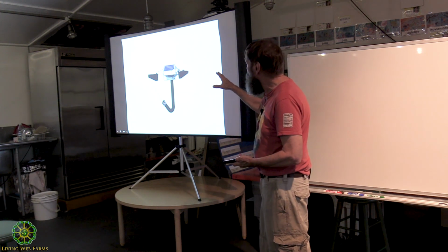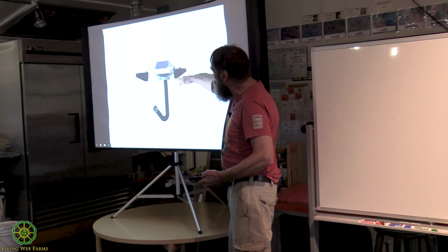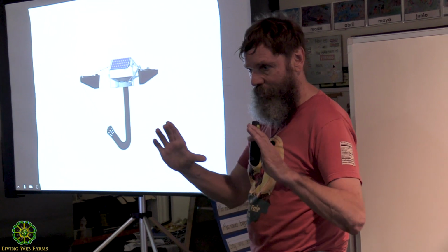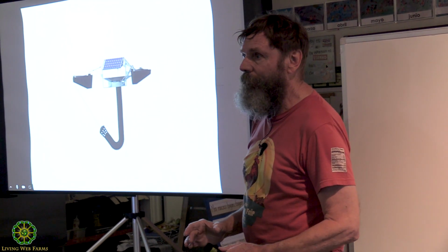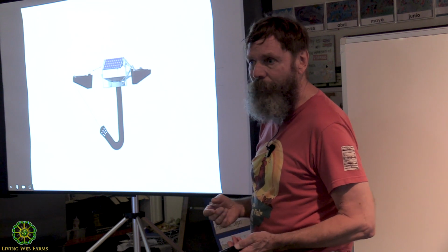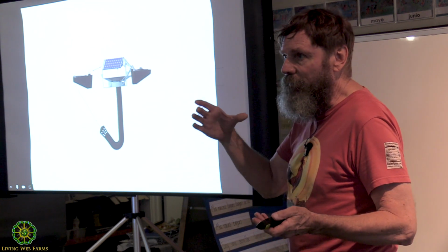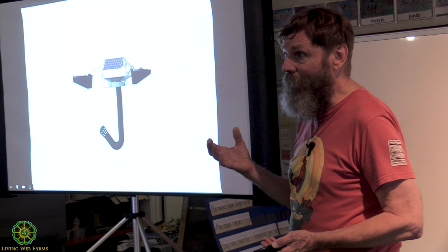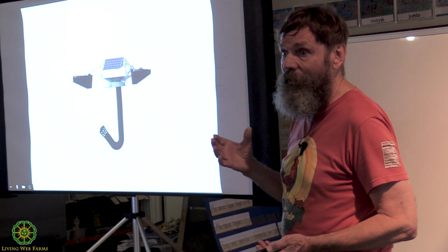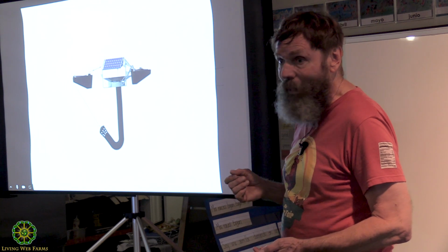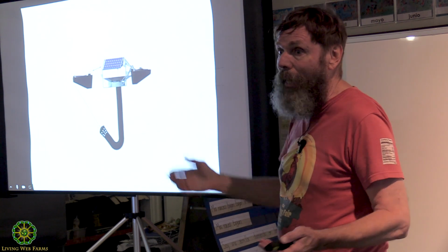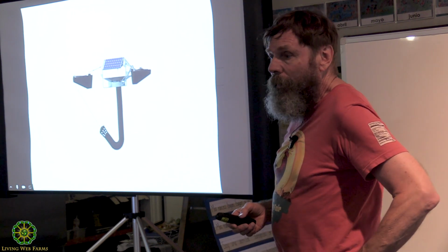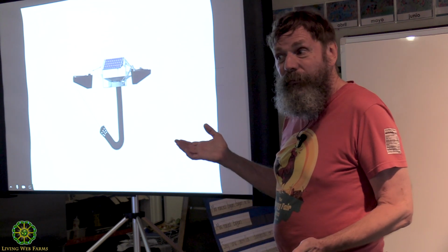What we'll basically be doing is using the lower half of this on a much smaller scale, in the range of maybe a 10 or 12 inch diameter draft tube. We can use PVC pipe. If we don't want to use plastic, we can use a galvanized culvert. If we don't want to use the galvanized, we can maybe coat it with some kind of anodization, and it won't be chemically as bad. We could use just mild steel, regular pipe, or fabricate something out of our shop materials. Essentially, we're looking at a depth of maybe 12 feet in our case.